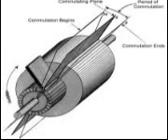A 4-pole generator frame is also shown in figure 9-10. In small generators, the frame is made of one piece of iron, but in larger generators, it is usually made up of 2 parts bolted together. The frame has high magnetic properties and, together with the pole pieces, forms the major part of the magnetic circuit. The field poles shown in the figure are bolted to the inside of the frame and form the core on which the field coil windings are mounted.